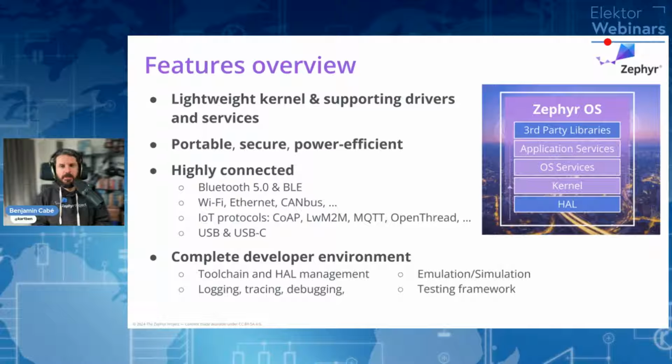Similarly, Zephyr provides you on top of the kernel with what we call operating system services, like APIs for interacting with the file system, APIs for interacting with the display controller, APIs and a model to really have a good abstraction of all the various peripherals that you might be manipulating, right?